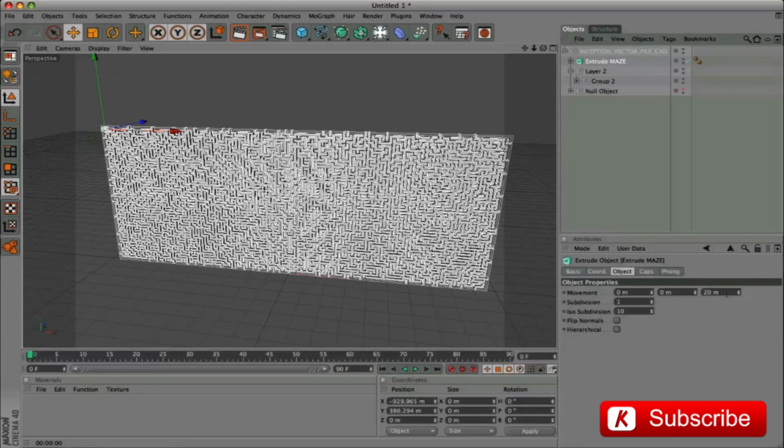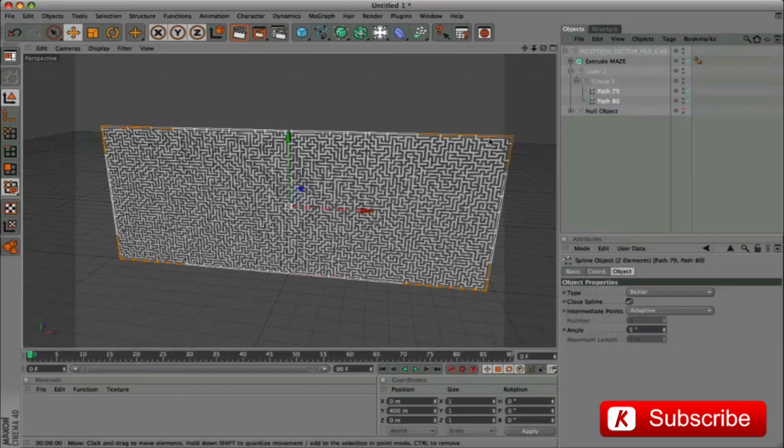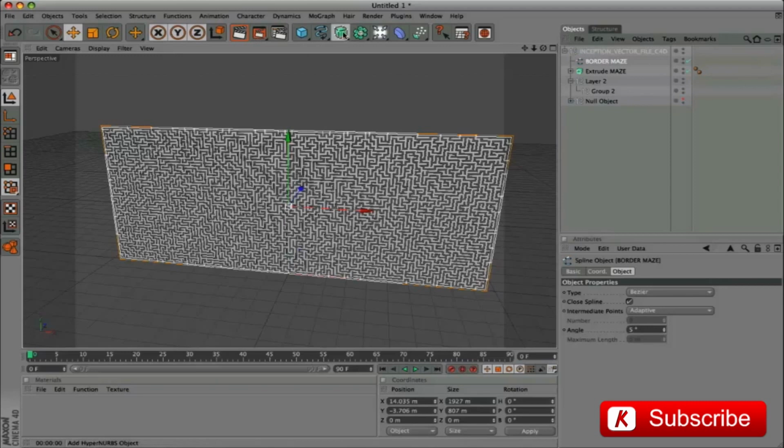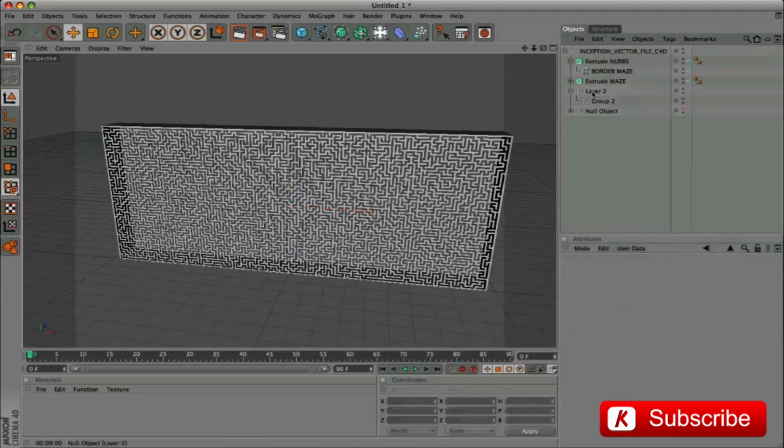We apply an extrusion depth from 20 to 2. We select the 2 splines in the group 2 layer and merge with the command Connect plus Delete. Rename it border maze. Drag it out and apply an extrusion with value 150. Delete the group 2 layer and the 2 layer.